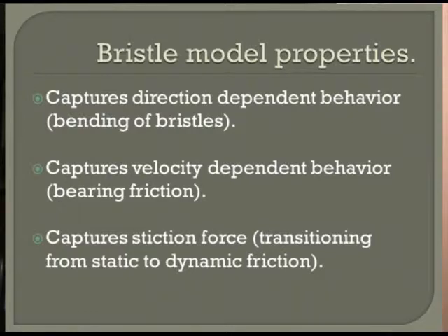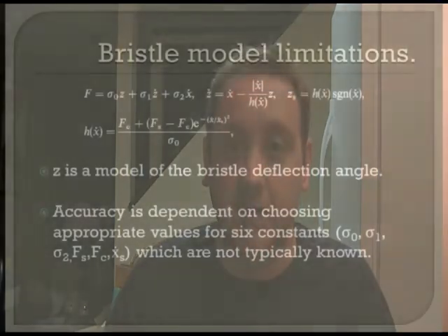In addition, it captures the stiction force, which my best understanding of it is a system that is on the verge of transitioning between the coefficient of static and sliding friction, has this stiction effect where it could potentially vary its resistance repeatedly.